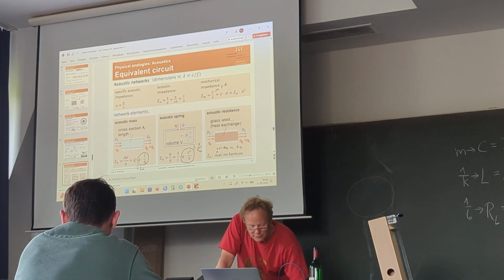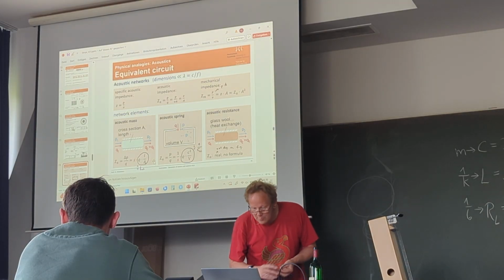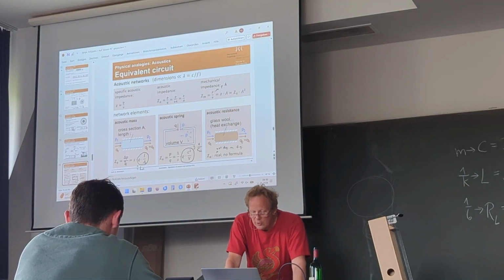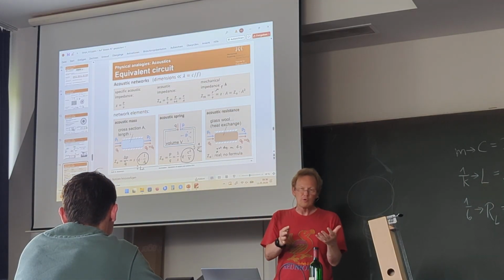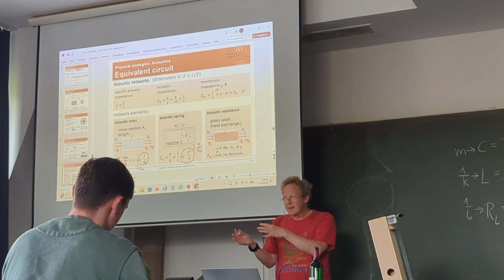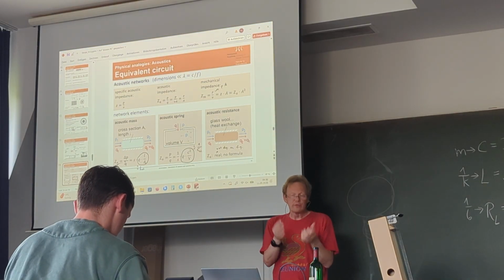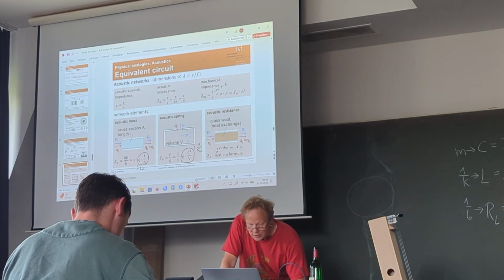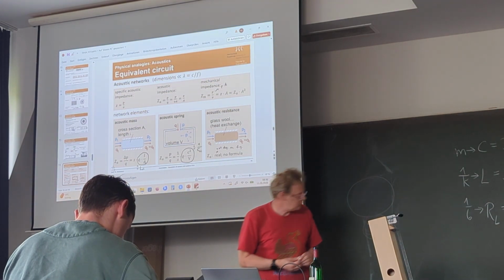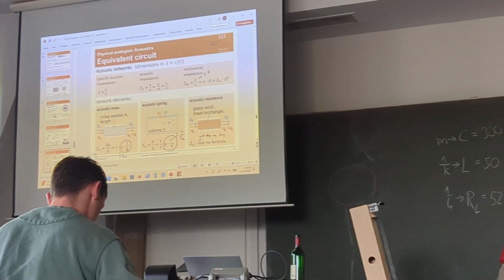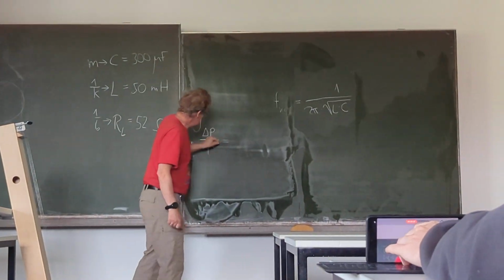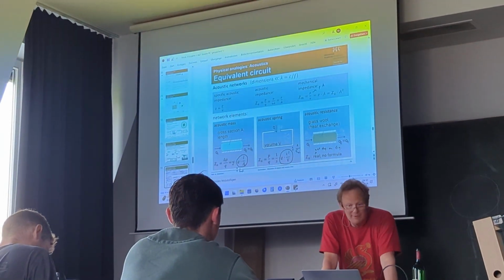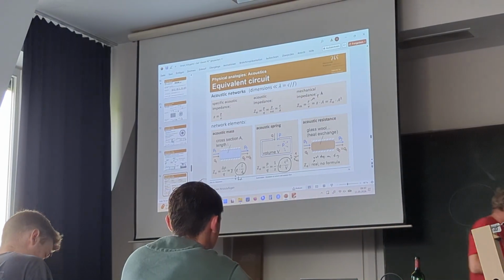Okay, here's a formula which is an impedance. So we have a ratio of pressure, and Q was the so-called volume flux. That means there's a certain volume. The volume changes in a certain time, or we transport a certain volume in a certain time. And the ratio is this volume flux Q. And we have the formula delta p over Q is, and then we have this strange s, which is the Laplace variable, multiplied.